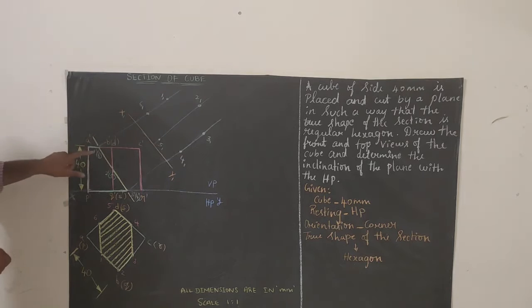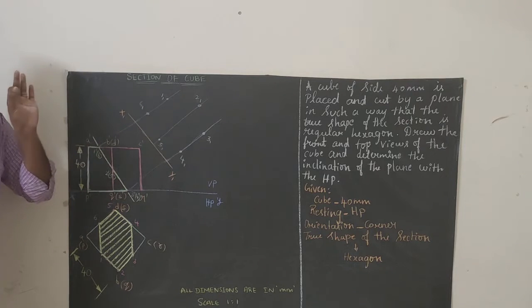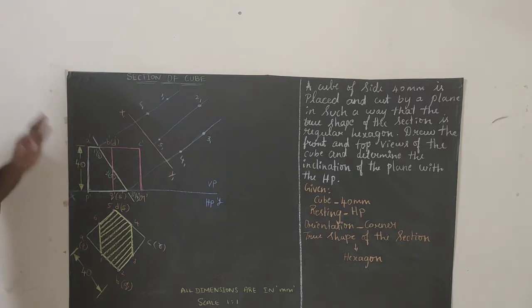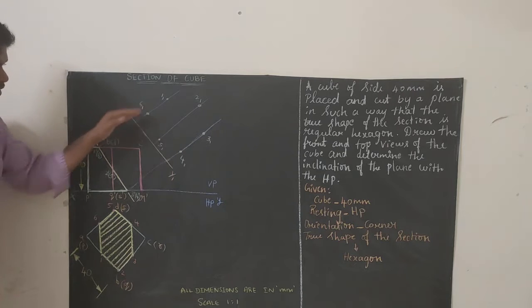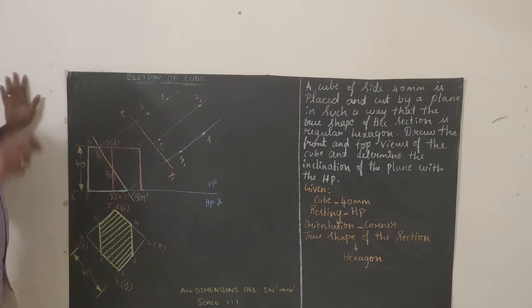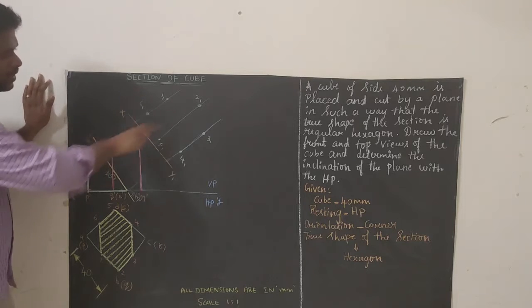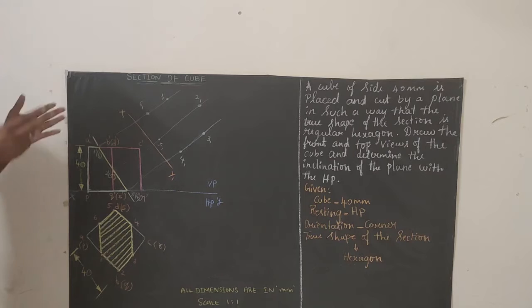How to extend this? See, here we have 6 cutting points, right? 1, 2, 3. From the cutting points you have to extend the lines perpendicularly. You have to keep on extending all the lines perpendicularly, 90 degrees. Just extend all the lines. These lines should be drawn with your 2H pencil. Draw very lightly. Extend all the lines vertically, perpendicularly.